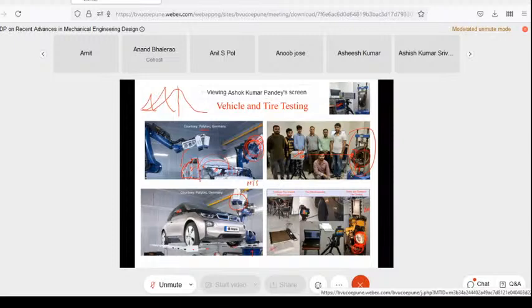You can just drive your vehicle on top of it. You can see the mark here, the vehicle. In this vehicle we tried to test. So here the vehicle will move on. The moment it goes over it, it will give you the tread information and the contact pressure. After you get the contact pressure, what you really get is the area over which the tire is in contact for a given pressure. Based on the pressure, you will see that the contact will also change.